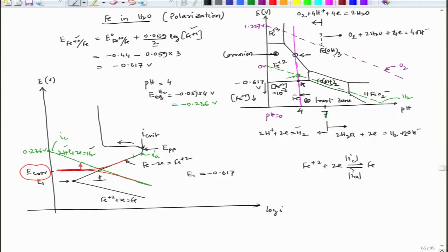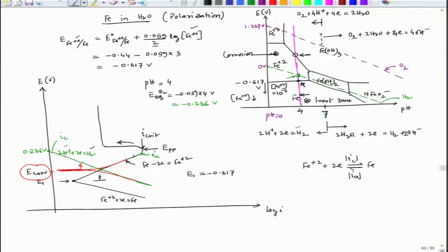Once it covers the metal surface, the electrolyte is seeing Fe(OH)3 rather than Fe, and Fe(OH)3 is a hydroxide with a very low solubility product. That means the iron Fe3+ concentration in the solution would be extremely low. So, the dissolution would be decided by the solubility product of that Fe(OH)3. So, the corrosion rate or the dissolution rate or the I_A should reduce, and that reduction happens rapidly, and then it appears as I_P, because this I_P corresponds to the dissolution rate as decided by the solubility product of Fe(OH)3, or the other way around, the ion movement from the metal surface to the electrolyte.